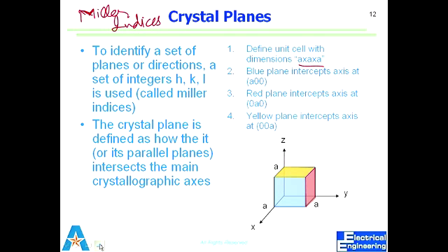Oh, I just showed you that number. What was the 5.24 angstrom for? So we call them 100, 200, 210. What that defines is, we generalize the indices to know what plane is available on the top, without going into how deep the unit cell is, because that is constant for silicon, for example. But the plane that is available may be different.